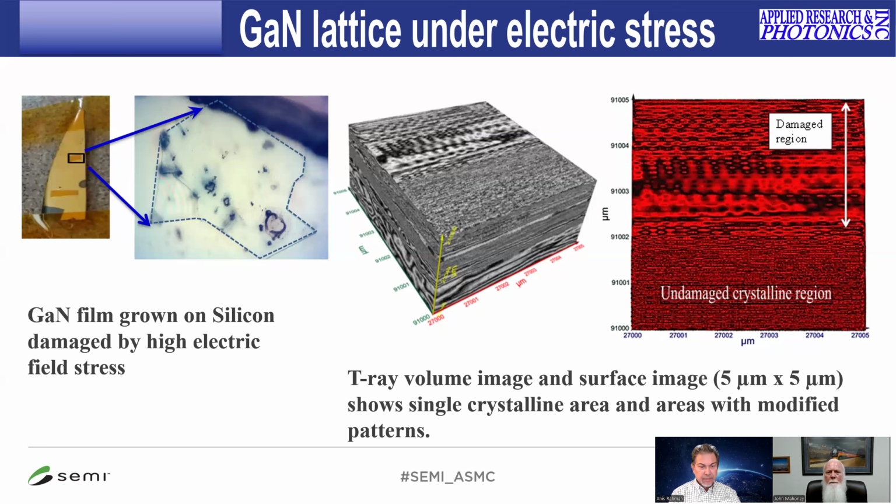Both SEM and TEM can see and image the lattice structure. However, for SEM, it's only the surface we are imaging. Therefore, what is happening below the surface is not probable until we take a cross-section and image that way. And in the case of transmission electron microscope, we have a very small area as well. We can see the lattice image of that small portion.